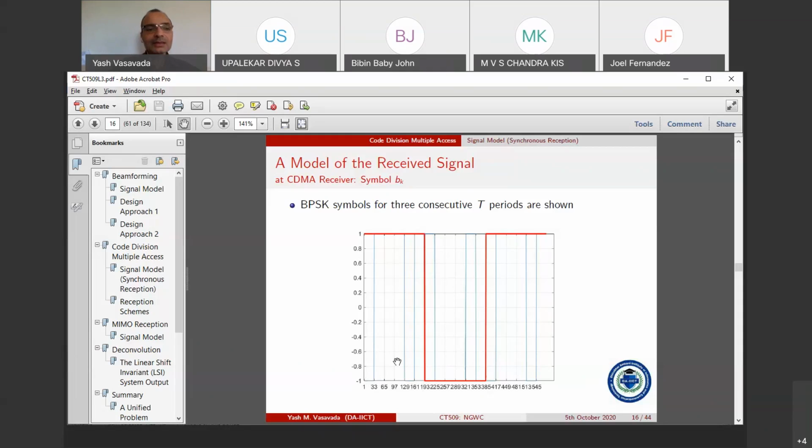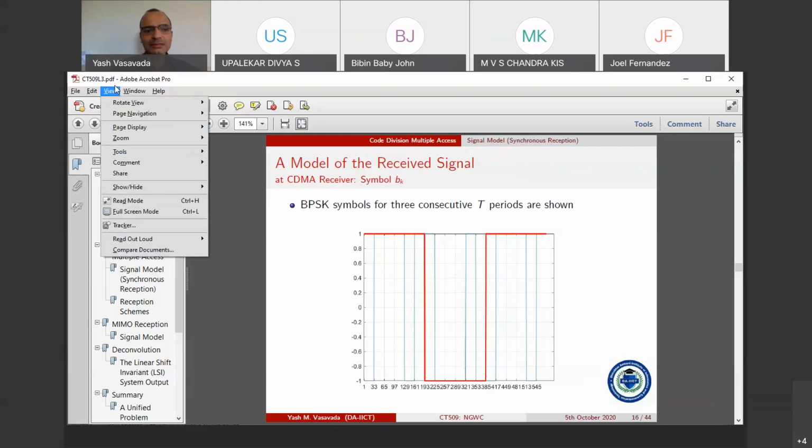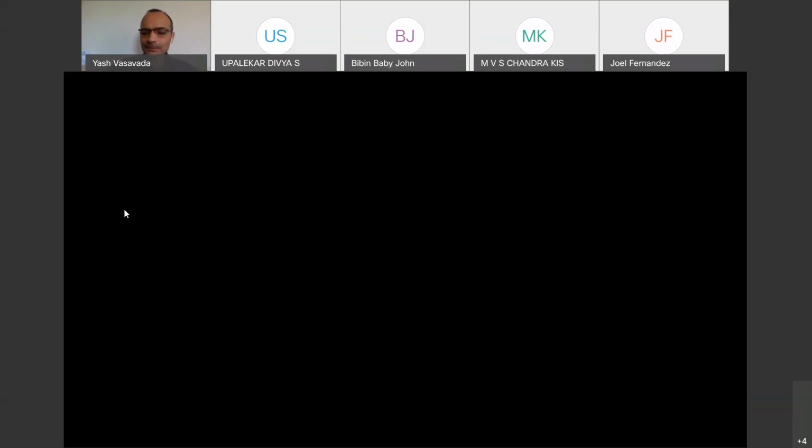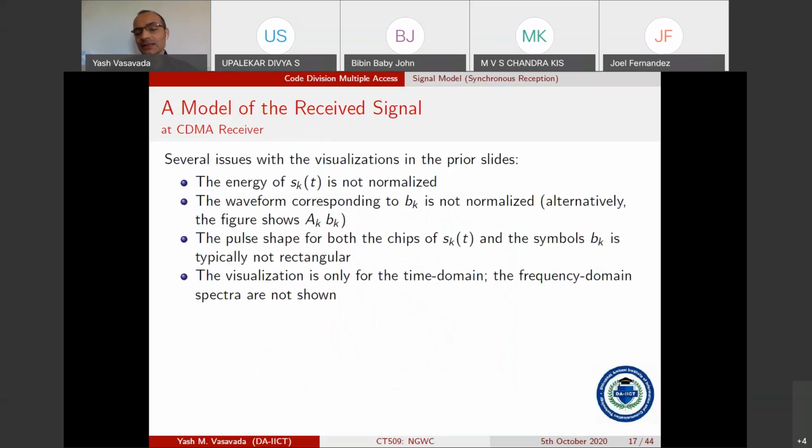And so that is why this scheme is sometimes also known as spread spectrum scheme. So that is something that you have to consider, that by doing this code division multiple access, I'm spreading the spectrum. Whenever in time domain we start making changes faster, in the frequency domain, we get a spreading effect.